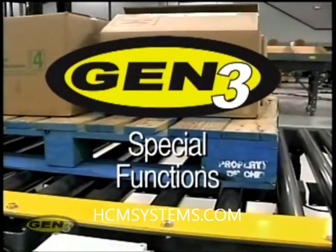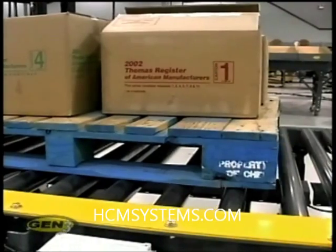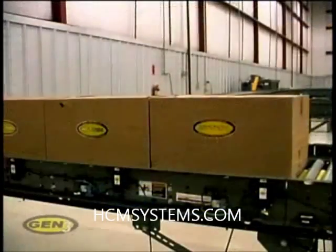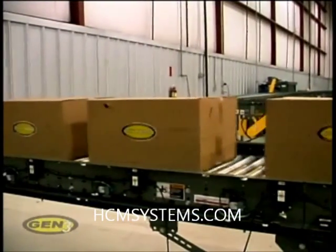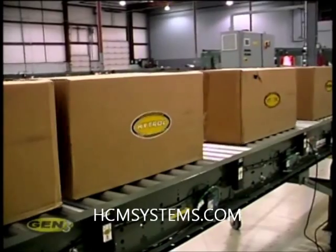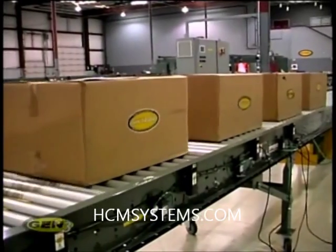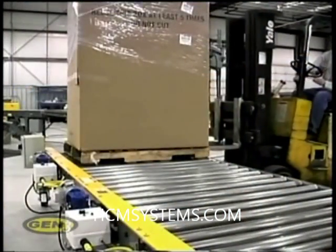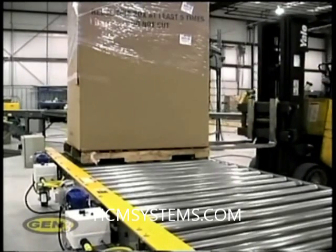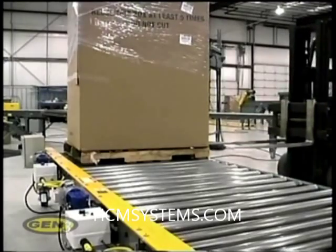Special functions. The EZLogic system offers a variety of special functions. Some of these functions enhance product flow. For example, the cascaded slug release function creates spacing between cartons as they are released from the conveyor, even if the conveyor is operating in slug mode. Other functions are designed to reduce the need for external controls. These special functions include loading and unloading functions for pallet handling and indexing zone stop control for workstations.